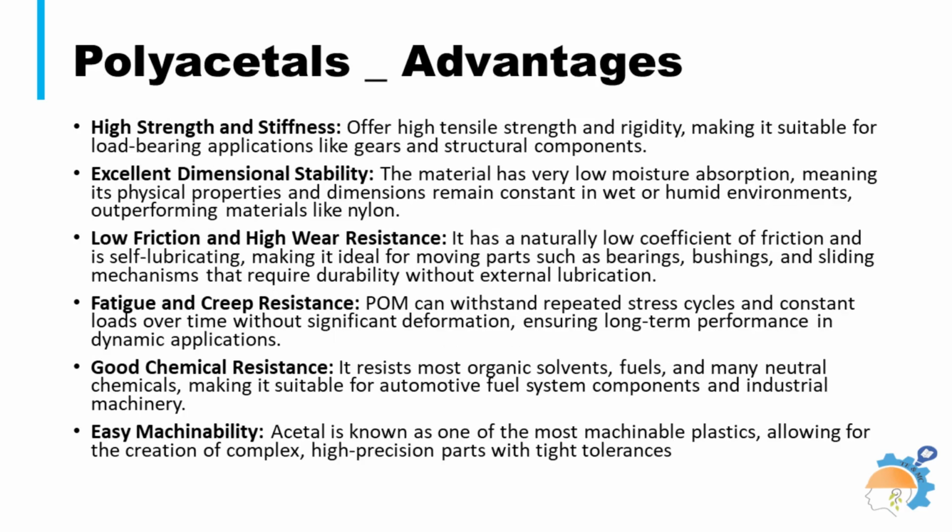Polyacetal, known as POM, resins are high-performance engineering thermoplastics prized for replacing metal parts due to their excellent balance of mechanical properties and easy machinability. Key advantages include high strength, low friction, and excellent dimensional stability, while primary limitations are poor UV resistance and difficulty in bonding.